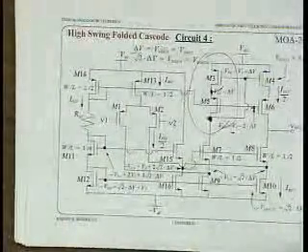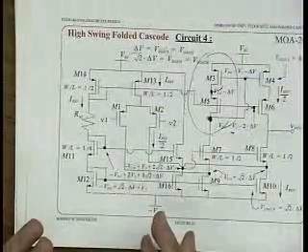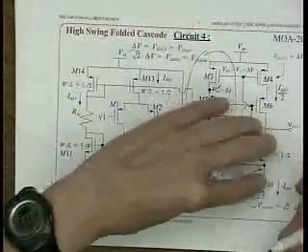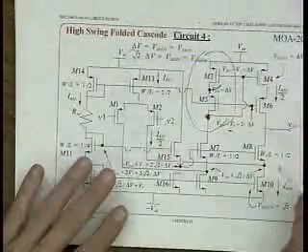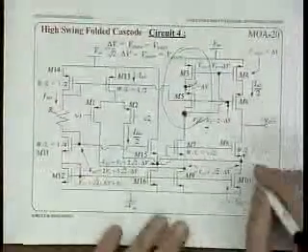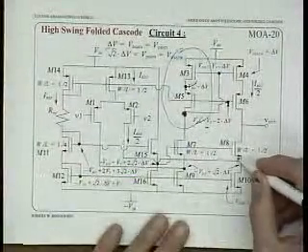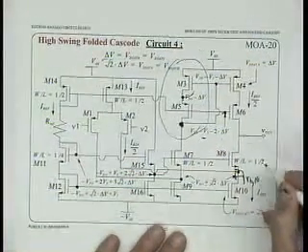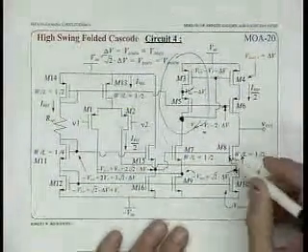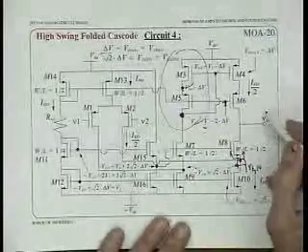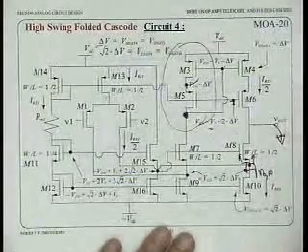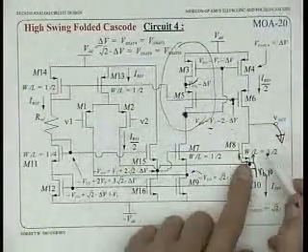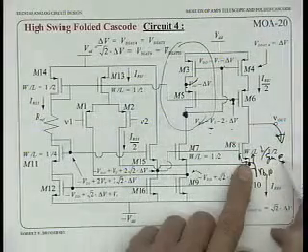Folded cascodes, because it's high swing, it's one stage. I mean, it's really one stage here, though we have this little bit of current. Let me just finish up what I said about looking down to here. What do we see looking down here? We see R0 of 10. Looking up into here, when I'm figuring out what the big GM is, I short this, right? And looking up into here, I'll see 1 over GM8.